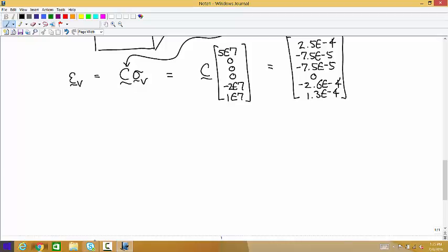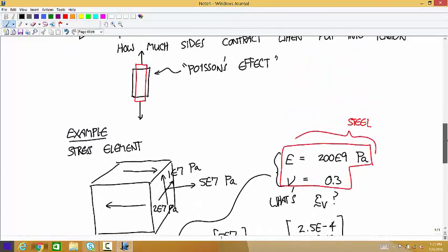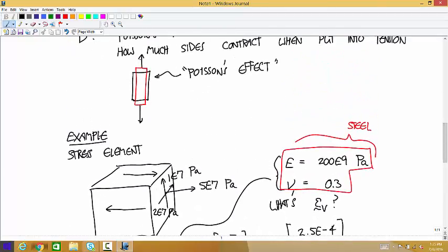A lot of times, if I'm not thinking about it, I'll draw something as if there's a point load, when what I really mean is we're going to treat it like there's a distributed load acting over that whole face. So really what I'm talking about here is a uniform distributed load acting there and there.